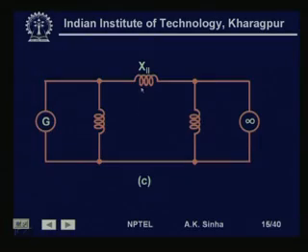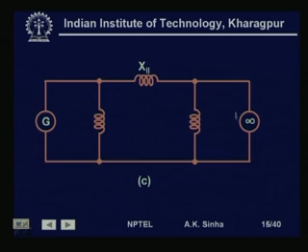So, this is what we get as the transfer reactance for the system. What we need to do is find out this x 2, and in this case the value of power transfer will be given by E dash V divided by x 2 into sin delta.